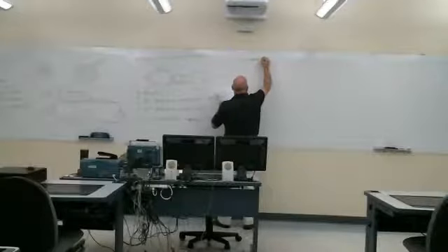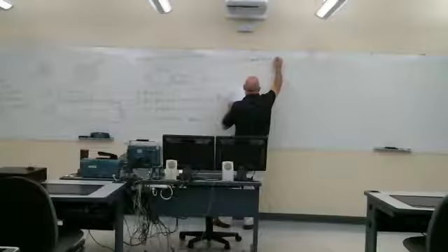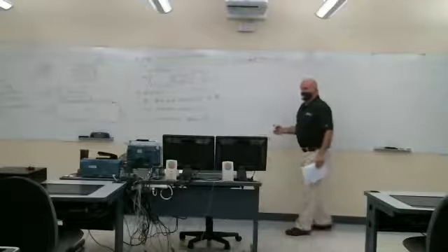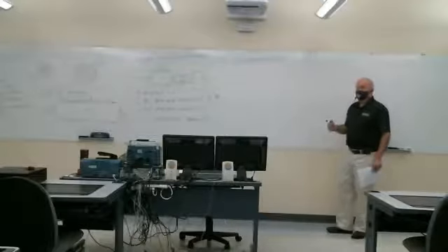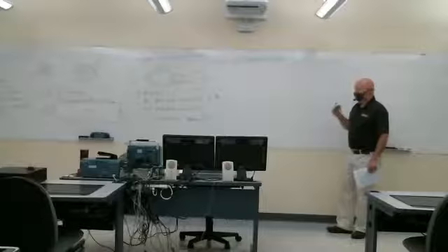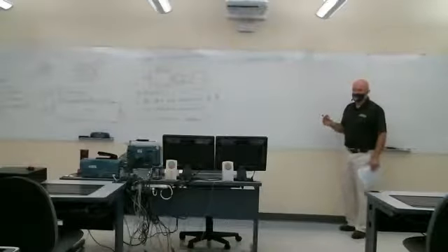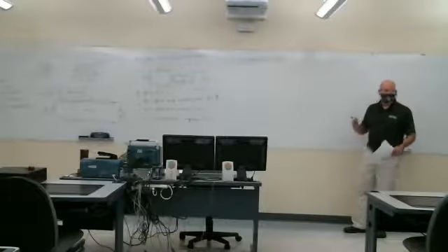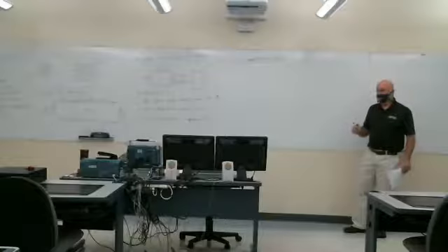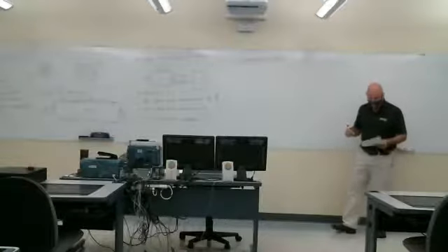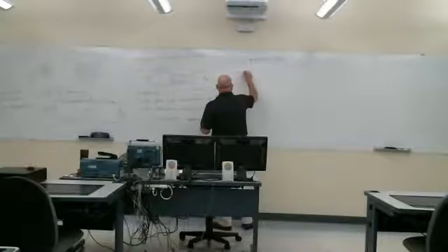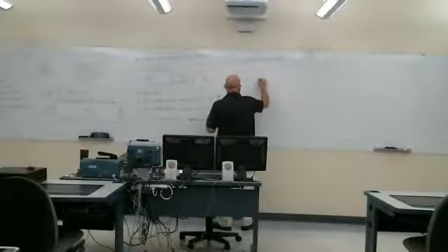Lumped element model. The first thing we want to do, though, is actually come up with a model for the transmission line. And our model is a differential equation model relating the voltage and current in the transmission line. You might expect that. That's how we have it from circuits. So the approach of coming up with this model is we're going to split the transmission line into small segments.